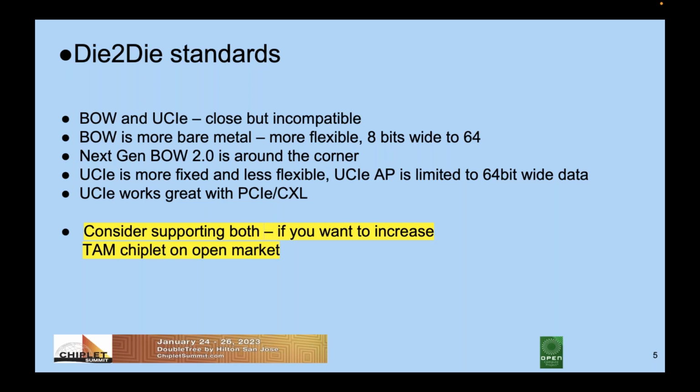Yeah, so you as a designer have a lot more choice, right? So let's say you want to do advanced packaging. UCIe has to be 64 links, right? It has to be tall and thin, the specific bump map. Maybe I shouldn't be going into that level of detail, but with a bunch of wires, there's nothing specified that's different between standard and advanced, right? So there's nothing to stop you from just doing a 16 lane, 32 gig per link implementation, right?